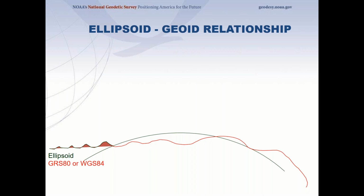Every time we use them, they're set defined factors for the semi-major and semi-minor axis and the flattening. The difference between them is very minute. It's the difference in the semi-major axis, I think it's 1 in the 5th decimal place.